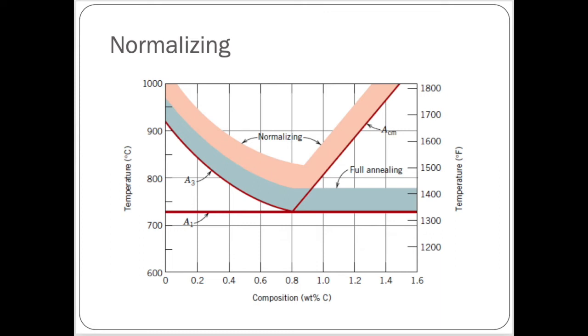An annealing heat treatment called normalizing is used to refine the grains, that is, to decrease the average grain size and produce a more uniform and desirable size distribution. Fine-grained pearlitic steels are tougher than coarse-grained ones.